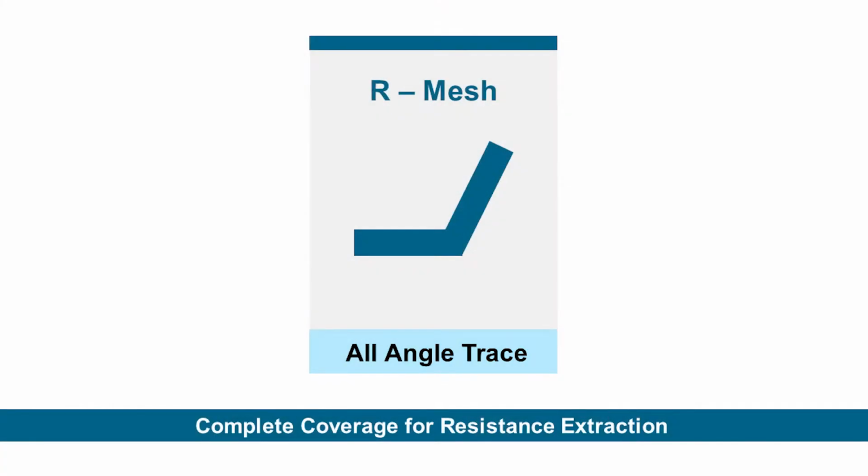The rule-based approach is not accurate when length over width, or aspect ratio, is close to 1, so it is hard to decide the current direction. This is especially true and more complicated when designs have non-Manhattan shapes with holes. Mesh-based extraction is targeted to improve resistance extraction accuracy on complicated slotted metal layers where current flow is difficult to determine. The target layout condition is PG mesh extraction with plenty of slots and multiple layers.